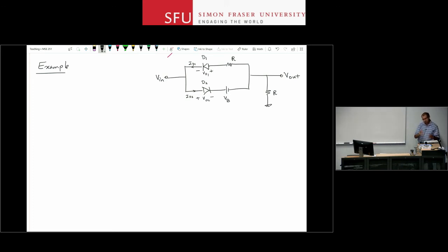With PN junctions, if you wanted to use the nonlinear equations, this cannot be done by hand. You have to spend a lot of time, or be really good at figuring out where the breakpoints are and focusing around those, and then other than those, assume a constant voltage drop or an open circuit and solve the circuit. Normally what helps is that you assume an ideal diode without any voltage drop to figure out the initial condition of the diodes and take it from there.